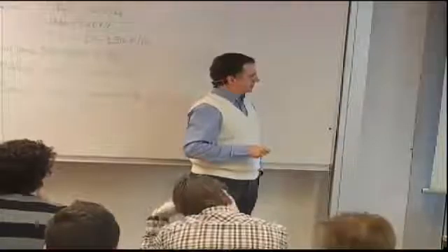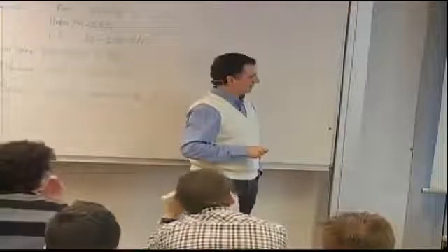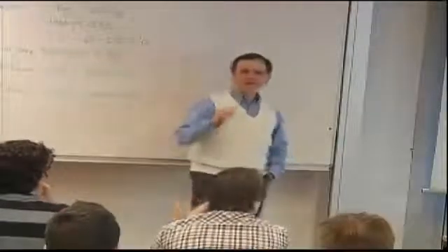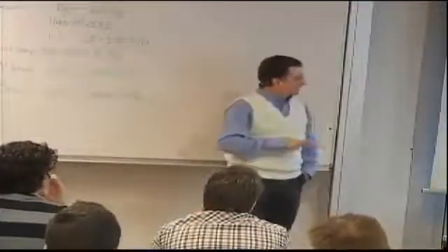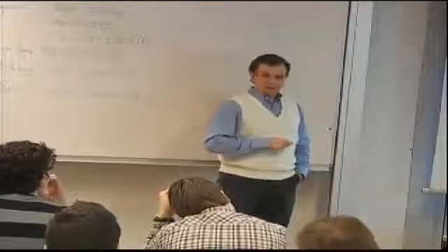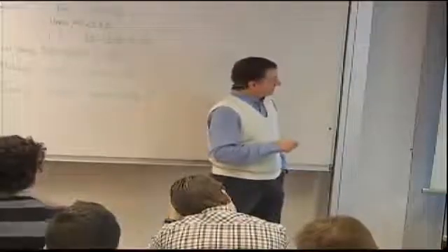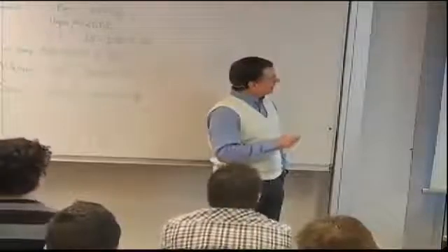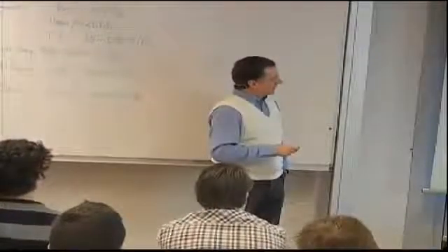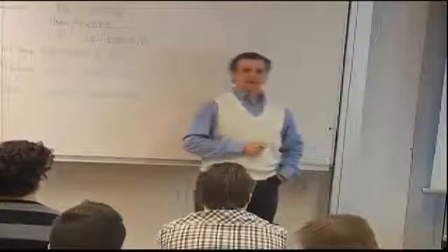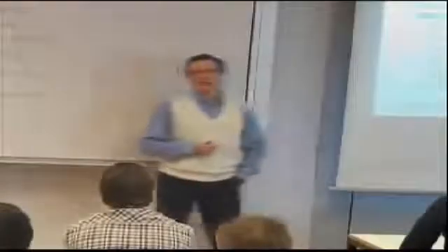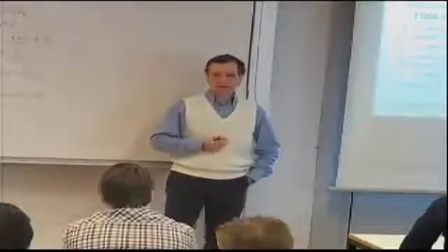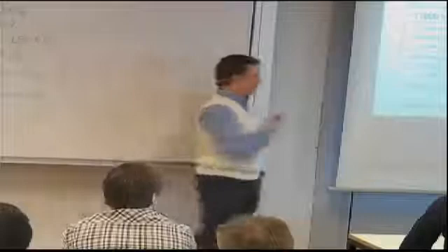This assumes a coefficient of variation. This at the bottom left here is meant to say CV, coefficient of variation of 11%, which is a bit on the high side, but it's good to cover most cases. It gives you another multiplicative factor of 0.8, or a 20% reduction. So if you take all these three together and you multiply by this 0.011, you will find 4,576 microstrain. And if you go and look at, ever since the 70s, the typical cutoff strain values being used in composites were 4,500 microstrain. So there is a reason which is very much strongly related to this.